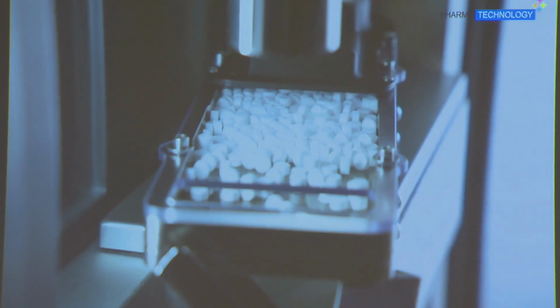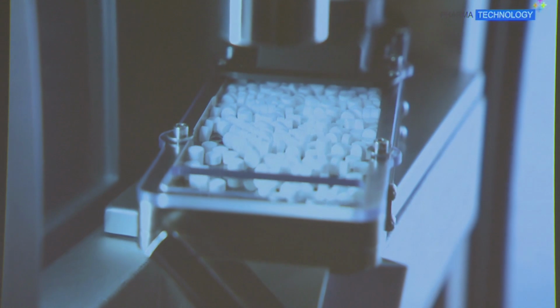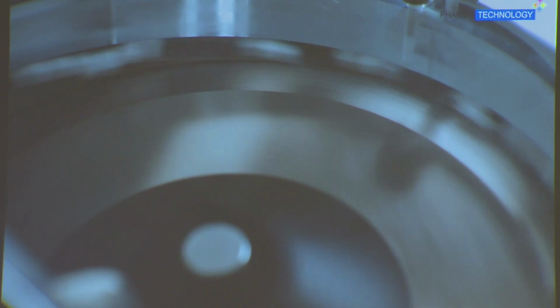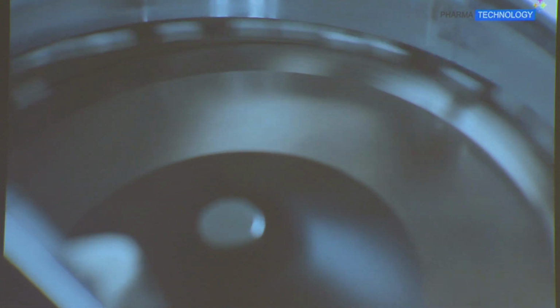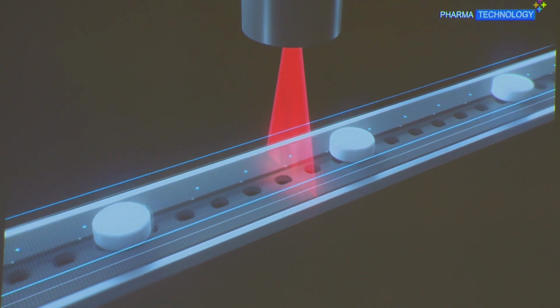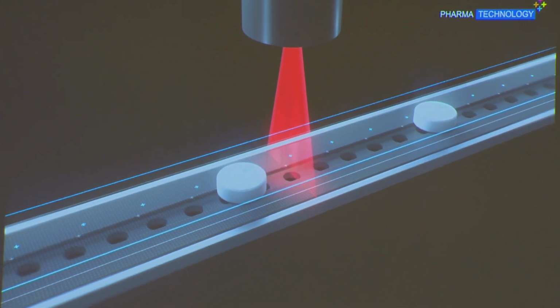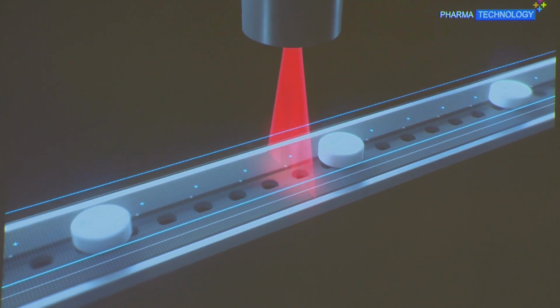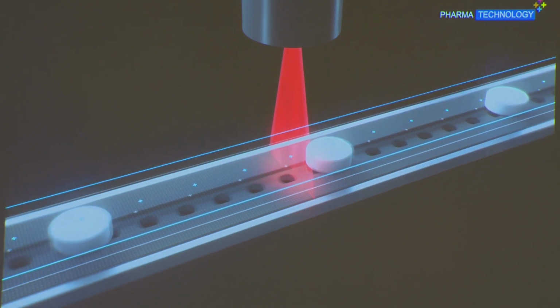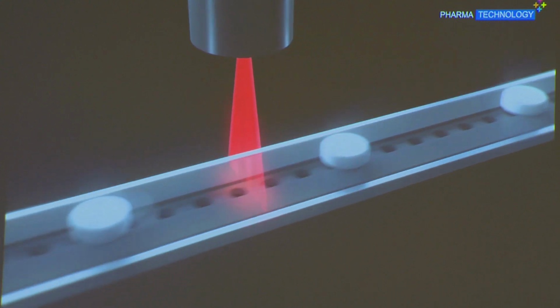First, the vibrating pre-feeder receives tablets from the hopper and doses them into the centrifugal bowl. From there, the tablets are lined and distributed one by one on the conveyor belt. The fixed speed vacuumed conveyor holds the tablets in perfect position and brings them to the 3D laser scanner. This 3D laser scanner verifies the exact position of the tablets and informs the NIR probe in real time to trigger the spectral acquisition with high accuracy. At the same time, the thickness and diameter are measured for each single tablet with an accuracy of 0.1 mm.